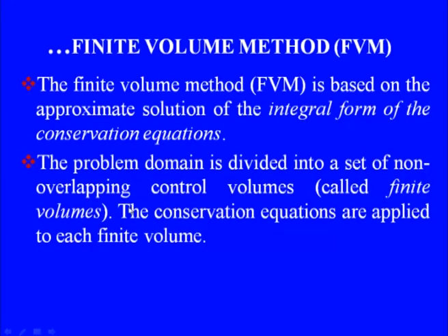And then what we can do is, the way we just described, the problem domain is divided into a set of non-overlapping control volumes, and since they are finite volumes, they were called finite volumes. We can now apply conservation equations to each of these finite volumes and take all of them together to obtain a system of discrete algebraic equations, which can be solved in the same way as we did in the case of the finite difference method to obtain a solution to our problem.